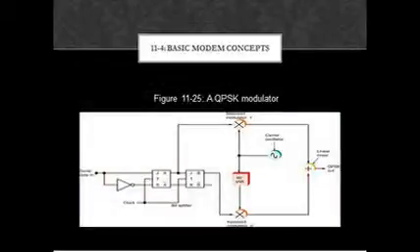A circuit for producing quadrature phase shift keying is shown in Figure 11.25. It consists of a 2-bit shift register implemented with flip-flops, commonly known as a bit splitter. The serial binary data train is shifted through its register, and the bits from two flip-flops are applied to balanced modulators. The carrier oscillator is applied to balanced modulator 1, and through a 90-degree phase shifter to balanced modulator 2. The outputs of the balanced modulators are linearly mixed to produce the quadrature phase shift keying signal.